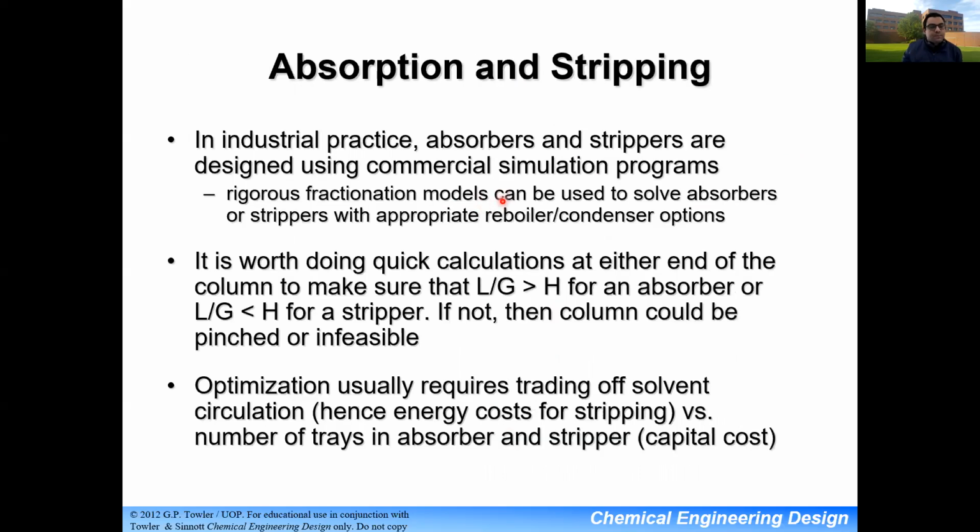All right. So again, in industrial practice, absorbers and strippers are designed using commercial simulation programs. Most of the time it's Aspen Plus. Sometimes there are other unique packages which do this design, because the calculation becomes a bit complex as I have a bunch of stages and my solvent becomes saturated. If the gas is hot and the solvent is cold, I also have a heat transfer effect. So now equations are starting to pile up, right? So it becomes easier to use a simulation package. And you can always do a back-of-the-envelope quick calculation to check your L over G and all of this stuff.